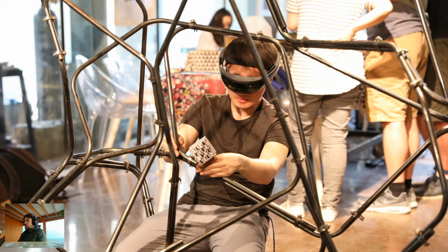Another extension of using very, very cheap analog tools combined with the sort of digital precision of holographic models is in being able to digitize physical things while they're being built. So when you put a fiducial marker out in front of the HoloLens or in front of a mobile phone with Fologram, you can track exactly where that marker is in space. And if you run it along a physical object that you want to digitize, you can get an approximate sense of the geometry of that object.